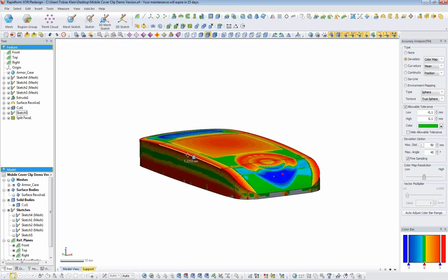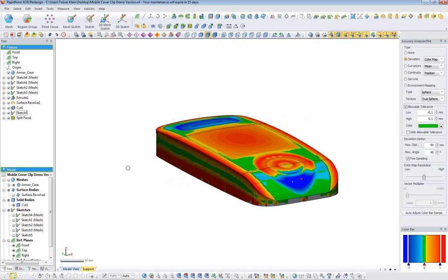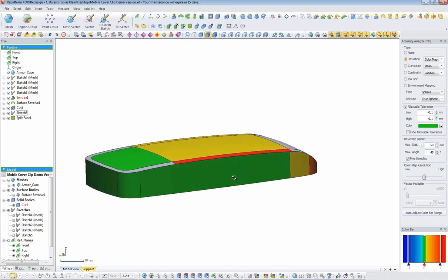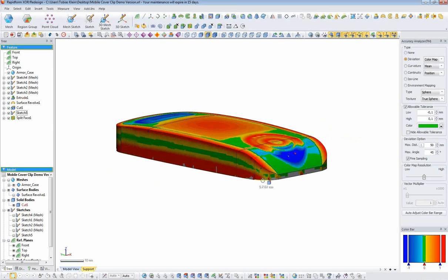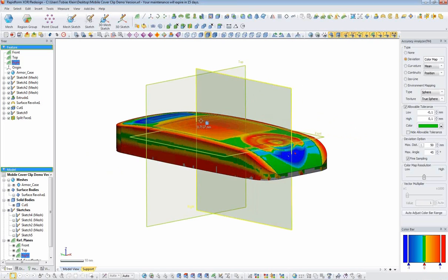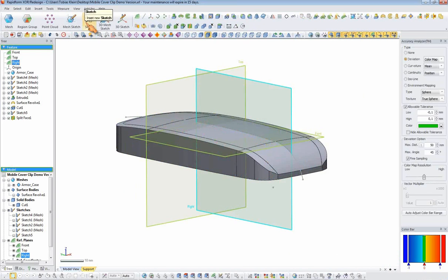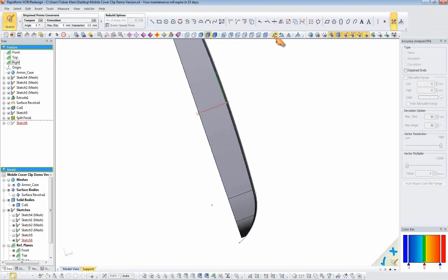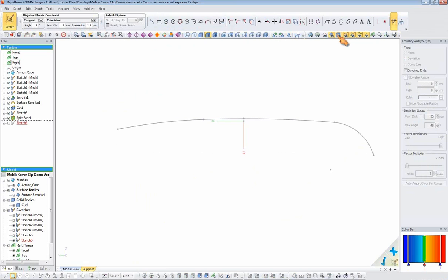So we will make a chamfer around here. Basically it's a loft, but it would look like a chamfer. So in this case we need another line around here, and we can draw that line again reusing another line which we drew before. So we have this line already, so I can use this plane and create a sketch on that plane. And I can reuse this line, convert it, make it a construction geometry,